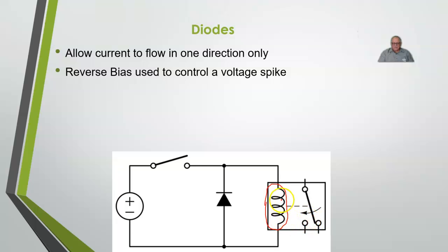When we shut it off, this magnetic field collapses down, and as it collapses down, it's going to induce a voltage into itself. That's our voltage spike. That voltage spike can get into dozens or even hundreds of volts. When you start getting up into the 50 plus volts, if that voltage goes over and makes its way to some transistors, it can actually damage the transistor or even destroy the transistor.